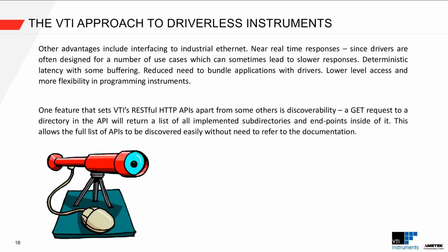So other advantages to using RESTful HTTP, it means that it is able to communicate and interface with industrial Ethernet. Ethernet at the end of the day is Ethernet, but now we can work on systems that have time deterministic configurations. Because we're just calling a simple layer on a web page, we've got near real-time responses, and the reason for that is drivers quite often are designed for a number of use cases.